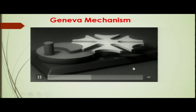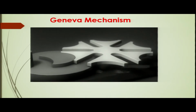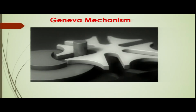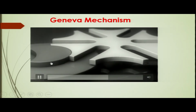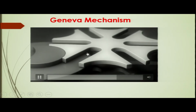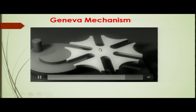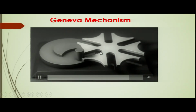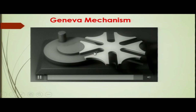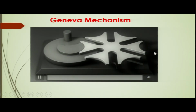Okay. So, it is then indexing when you need the output shaft to index, and the transmission is the continuous rotation of the input shaft. This is the input shaft. The pin comes in and goes out of the slot of the Geneva wheel. In that case, it is coming from one position to another position.